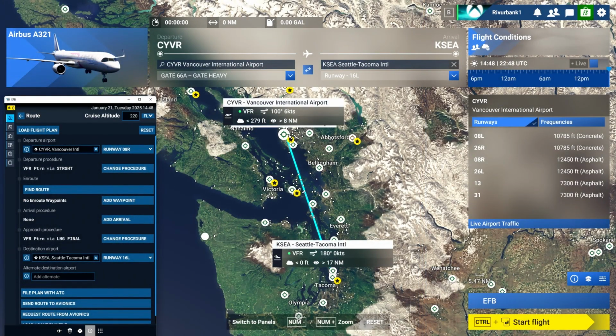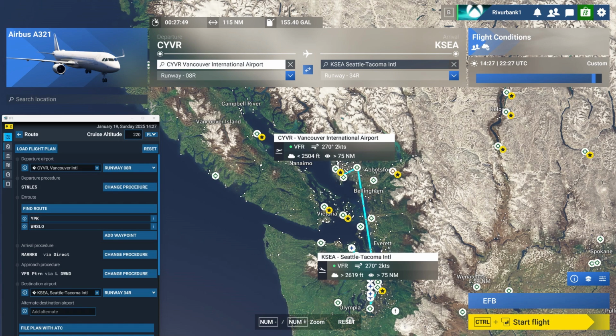So in the flight planner, you know you're going to select your departure and destination. In this case, I'm going to start at a gate because I want to go through the gate procedures and all the setup procedures. But in the EFB, you're actually going to have your runways selected. Departure runway, arrival, your SIDs and STARs, procedures. Now I forgot to set that in this sample. I did have to adjust the runway, but then I'm going to show you here what the actual procedures are selected. As you can see, departures and arrival procedures are also selected.